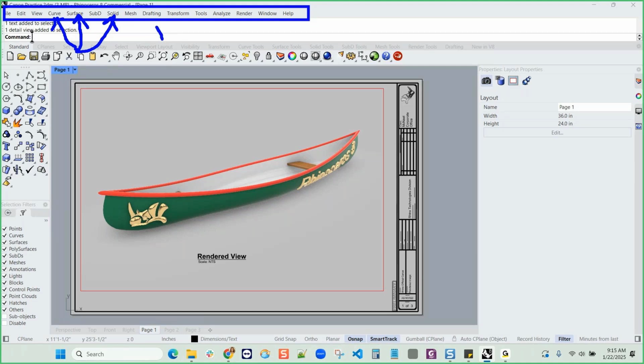We also see that Rhino has drafting features and transformation commands like scale, mirror, rotate, align, flow along surface, flow along curve. These are those commands that are going to take your geometry and morph them into different shapes, different arrays. And you can see here that this hull surface is curved, but the Rhino text is morphed to flow along that surface.